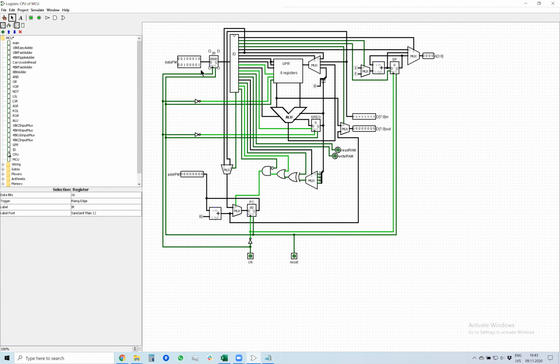It's temporarily saved in the instruction register, so it doesn't wiggle around during some processing in the processor. It's forwarded to the instruction decoder. The decoder forwards the bits of the instruction to their corresponding places in the CPU. So some bits are received by the GPR, some by the arithmetic logic unit.